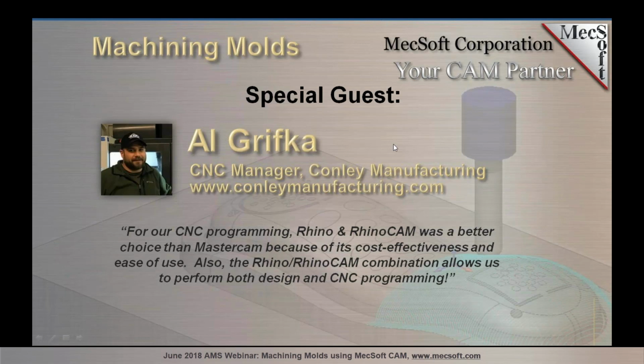So basically what we do is we'll replicate a fixture that will hold that particular part in a certain manner to be able to check it so that when the parts are coming down the line, they may pull, say, one out of every 5 or 10 or 20 parts and put it in this fixture and check it to make sure that their production process is working correctly, and it's a safe fail where they can catch bad parts coming down the line, and maybe they might have to alter some of their processes to make that part perfect every time it comes off the line.